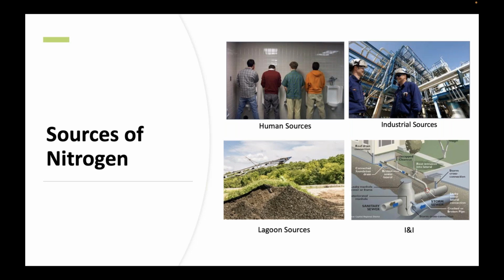And that then sinks down to the bottom and adds to the nutrients sitting on the bottom. So these things can feed back at certain times of the year. We have a whole module on lagoon biosolids, so I'm not going to go into it here, but there's something called benthic feedback, where the nutrients in the sludge, or nutrients accumulated over time, will actually re-release into the water column.